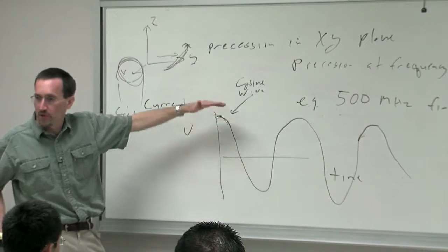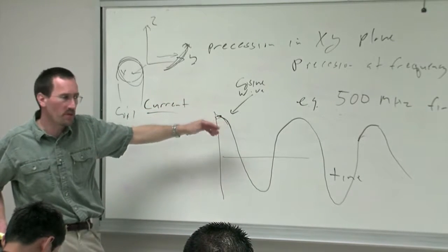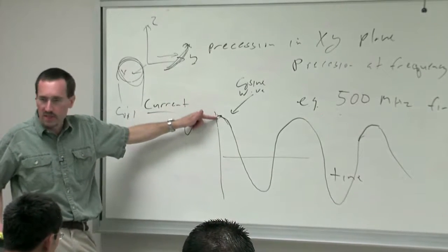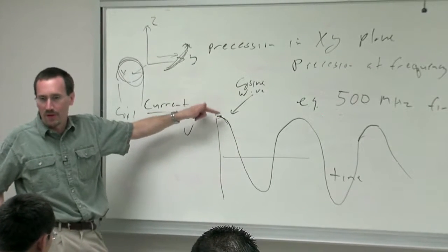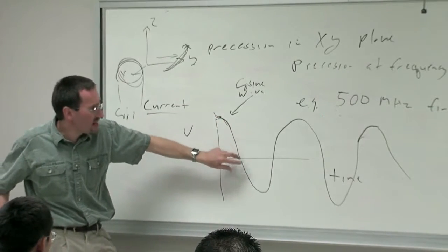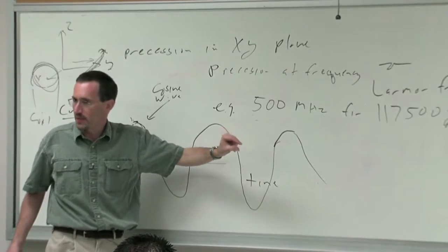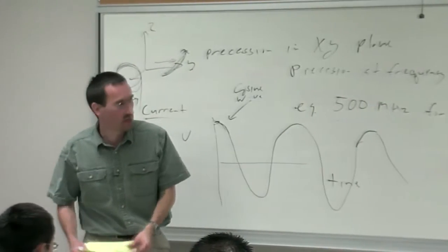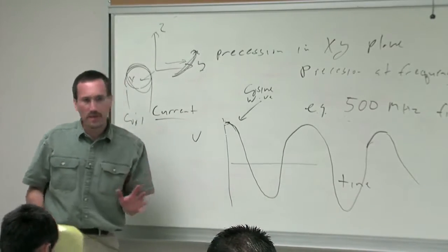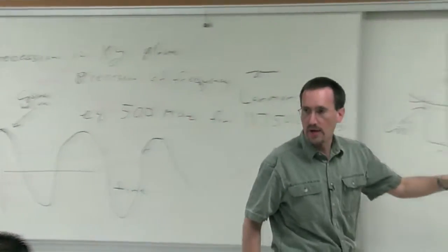But if it's bigger, you're going to saturate it, and then you're going to get all sorts of artifacts and clipping. But if it's too small, if you're representing your maximum signal by 0, 0, 0, 0, 0, 1, 1, 1, then by the time you're down to very small signals, you just don't have the digital capacity for them. So that's what you're doing when you're adjusting the receiver gain. OK, so that's my pigeon diagram of an NMR spectrometer and what's happening.